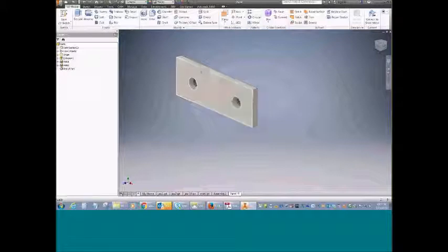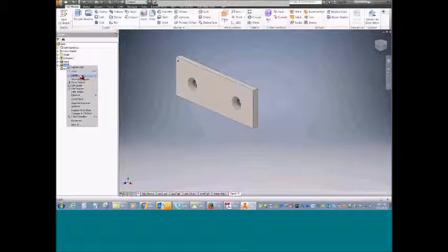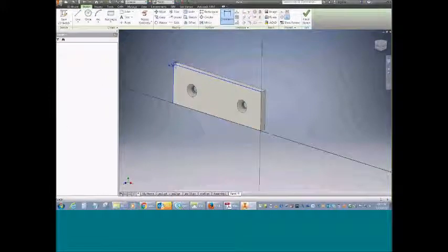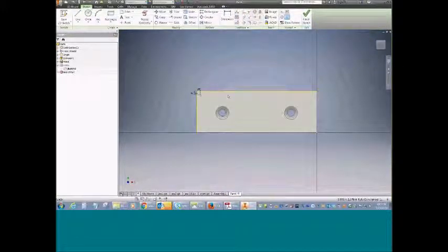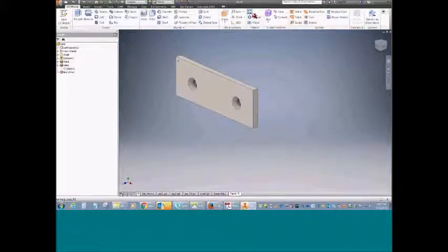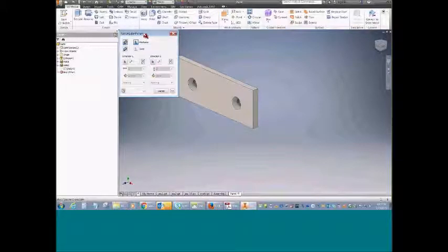And a couple of things you could do, I could have, let me go back to that sketch, I could have patterned this hole point, because there's a pattern feature here in my sketch plane, but I rarely do that. I prefer to have a finished feature and pattern that. Just works a lot better.